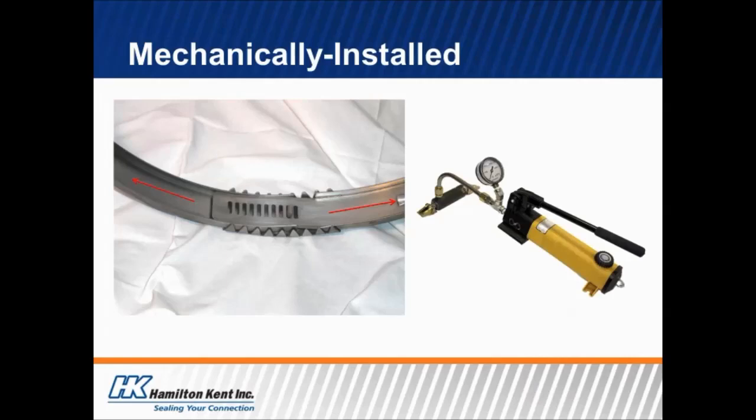This is another type of connector from a mechanically installed boot. You can see on the right-hand side is a jack that has 2 feet. They're kind of gold-colored. Those feet fit into notches that you can see, one of them just on the right-hand side of that picture of the hoop, and then the other one is off to the left. They fit into those, and then as the jack is tightened, it expands that hoop out, and there's little notches in the hoop, and as it tightens, there's a little tab here that snaps into place, and once you've reached the proper torque on it, then you're able to release it, and it's going to lock in place.